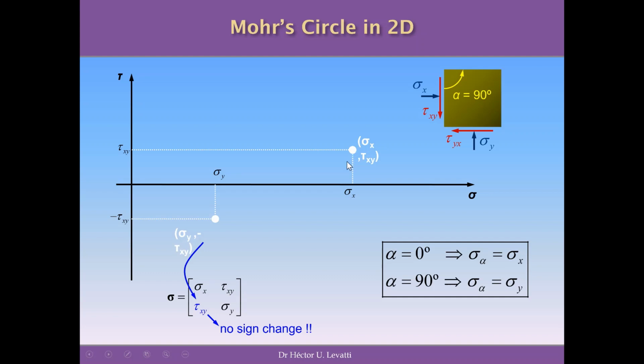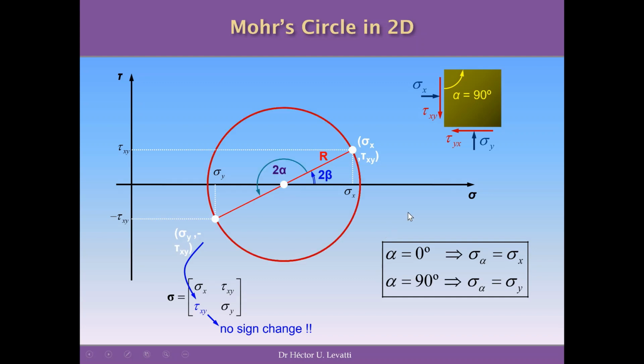And in this way, you can define with a line that allows you to find the center of your circle, the Mohr circle, and after that, with a compass, for example, you can define the radius, and you can define these angles as well, and you can define finally the Mohr circle for your problem. Automatically, when you have the Mohr circle, you find the principal stresses for this particular problem, and in here you have defined as well the angles you are considering for this problem and the equivalence between the stresses you have as data and the graphical representation in Mohr circle.